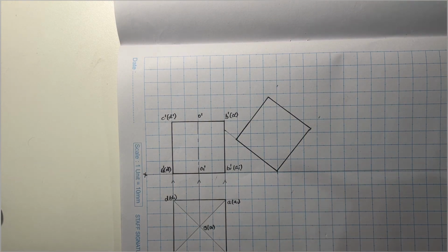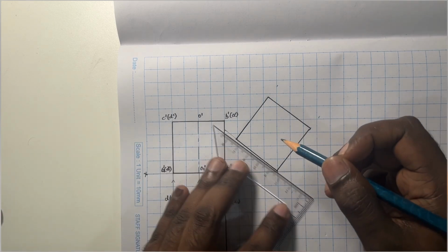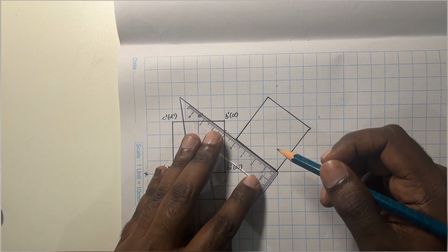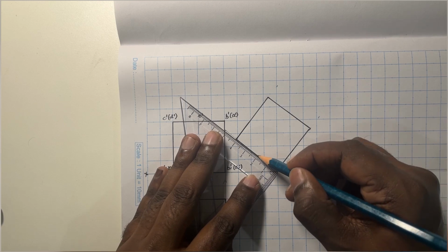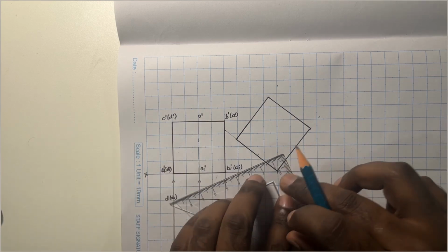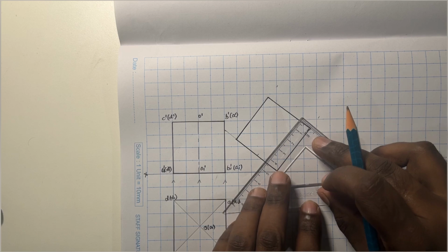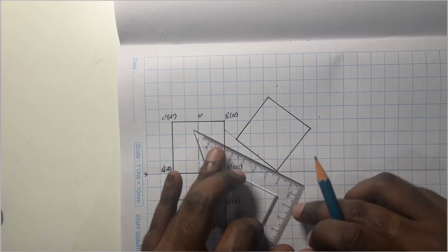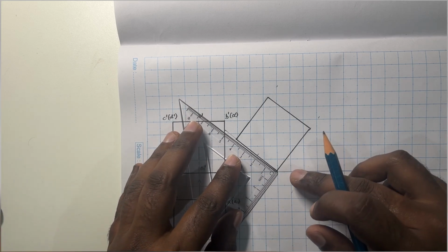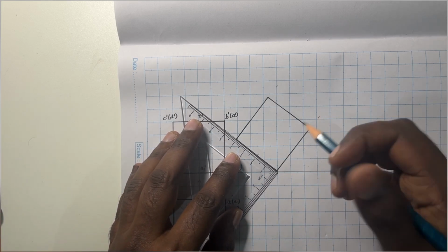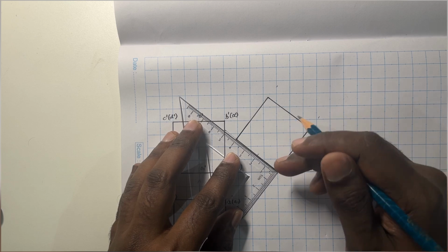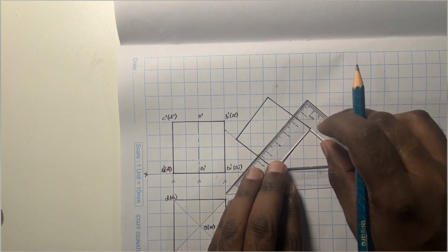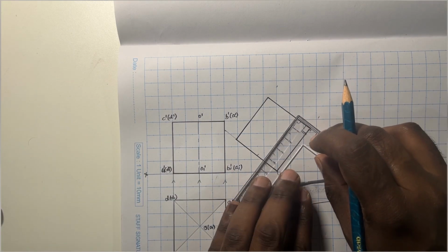However, I need to show the axis, and the axis is exactly at the midpoint. So let me mark the midpoint of this edge line, which is at 2 centimeters, that is 20 mm from this origin point. And this will also be a straight line. So let me use the set square to draw the straight line. Just glide your set square as if it is parallel and mark the center point of this particular cube. And now let me draw the axis line.